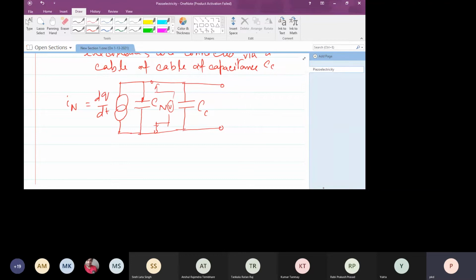If you connect two wires, the distance between these two wires will vary along the path. So the capacitance will not be constant. It will constantly vary depending on the position of the wire. So that will create a lot of noise in the measurement.